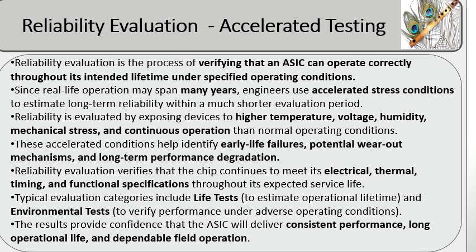The product reliability and life testing of an ASIC under real-time evaluation is a highly time-consuming process. Since real-time evaluation is time-consuming, statistical accelerated batch testing is carried out on a sampling batch basis. This methodology evaluates devices at accelerated temperatures, voltages, humidity, and electrical stress, and simulates long-term storage and switching life operation within a much shorter time.